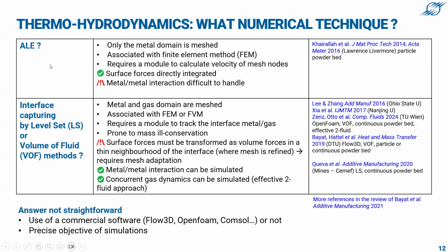So choosing between ALE and level set or VOF is not straightforward, I would say. It depends a lot on which software you use. Is it a commercial software proposing a solution or not? And it depends also on the precise objective of the simulations. Do you really want to simulate aerodynamics as well as the fluid flow or not?